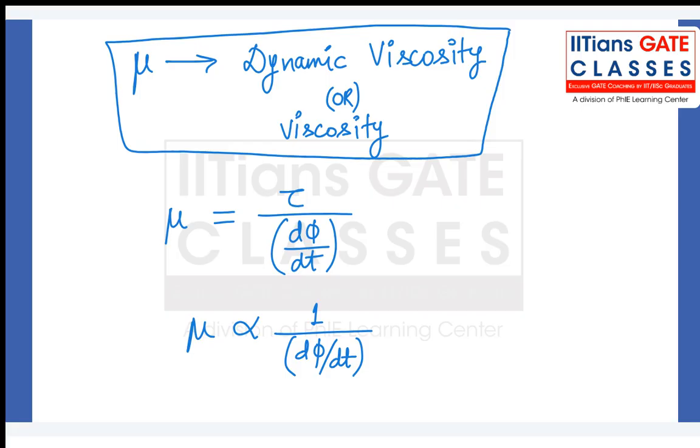So you guys answer one question. In one system, I have water. In another system, I have, let us say, some machine oil, lubricating oil. And I am applying the same quantity of shear stress. So which liquid will be easier to flow? Water. Why? Because it has lower viscosity. Yes, viscosity is low, so this means shear strain rate will be higher, correct? Yes, because viscosity is inversely proportional to shear strain rate.